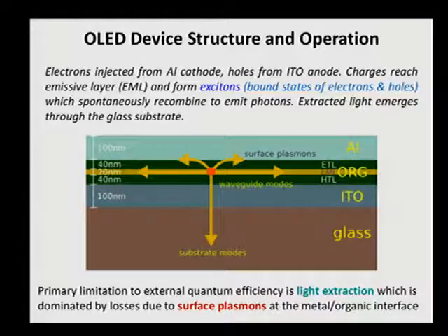Most of the light that's generated by the organic molecules does not in fact leave the device through the glass substrate. In fact, only about 20% of the total light that's generated actually leaves the device, which is a significant reduction of the device's energy efficiency. Light extraction is therefore a major area of research in OLEDs.